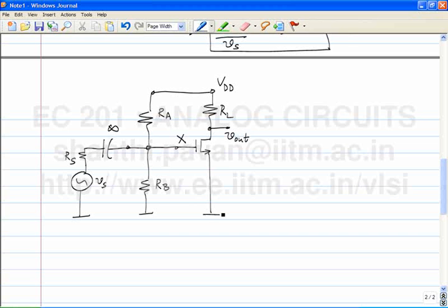You can add a capacitor. Okay, a more systematic way of deriving this would be the following. This is RL1, okay. I'll dumbly connect this here. What is the problem with this? Is there any quiescent current flowing through RL1? Yes. Okay, so that doesn't solve our problem. And so if you want to avoid quiescent current flowing through RL1, what do you do?